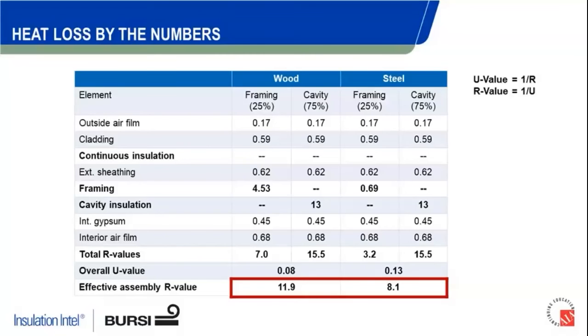So in order to get to our U value calculation, first I want to tell you that U value, if you don't already know, is measuring transmittance. So it's essentially measuring the opposite of R value. R value measures resistance to heat flow. U value is measuring transmissiveness of heat flow. So it's essentially the inverse of the R.